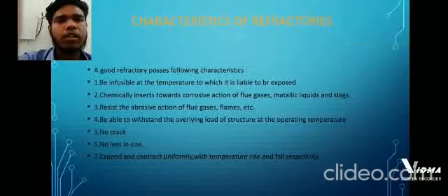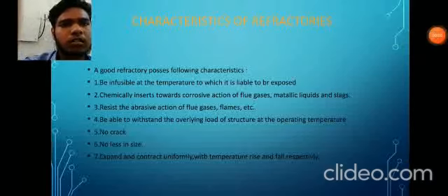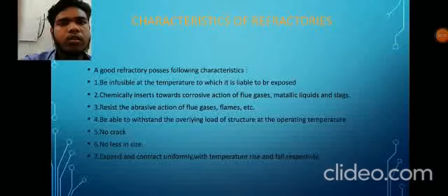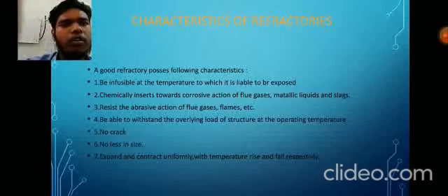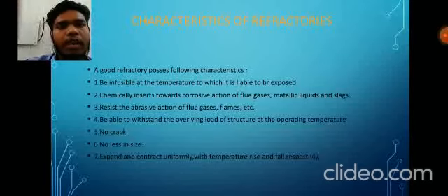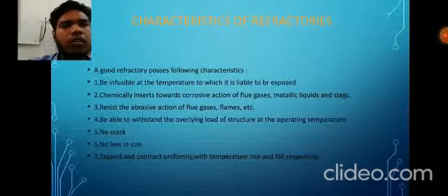Resist the abrasive action of flue gases, flames, etc. 4. Be able to withstand the overwhelming load of structure at the operating temperature. 5. No cracks, no loss in size, expand and contract uniformly with temperature rise and fall respectively.